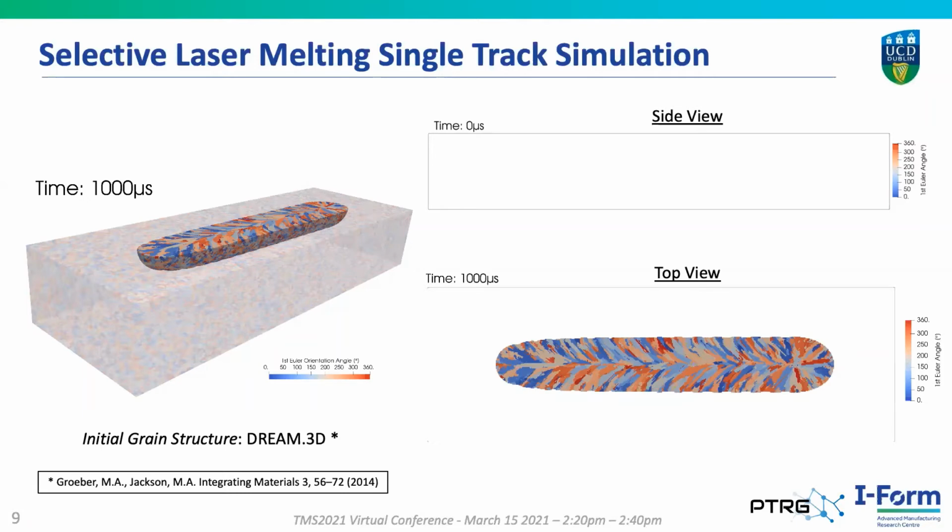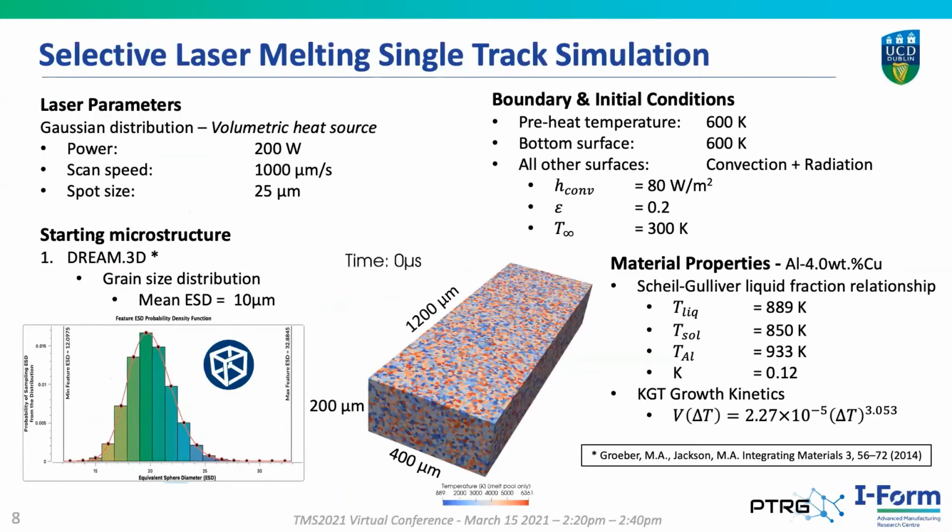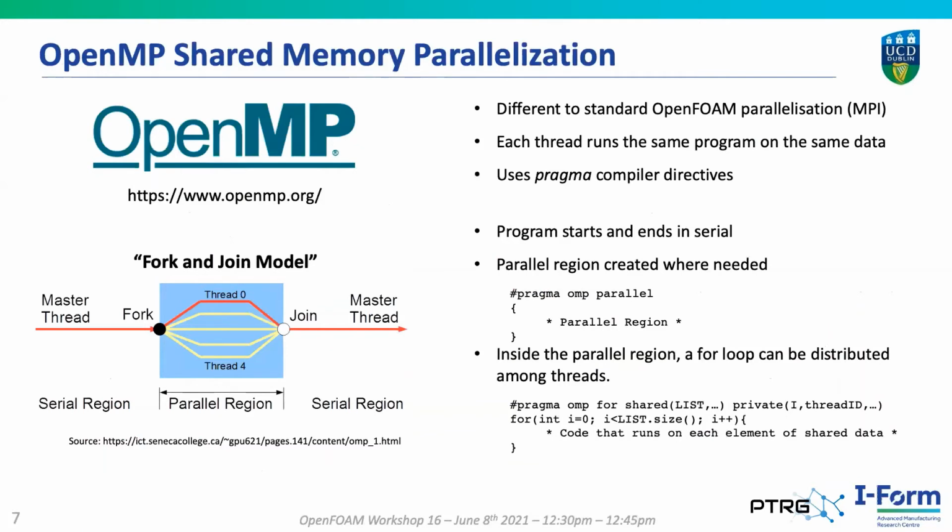Yeah, exactly. So the growth kinetics are generated specifically for a given alloy. Sorry, I'm not sure which slide it is. But the growth kinetics are generated specifically for a given alloy, so if I change the alloy properties, I'll obtain a different growth law polynomial. In terms of handling a mushy zone, my models are considered to be an envelope-based model, so I track the edge of the grain boundary and don't necessarily care about the detail inside the grain. Whilst inside the grain boundary it would be mushy, I don't really consider that. So these models are an envelope-based approach rather than a more micro-scale model like a phase field, for instance, which would track specifically the mushy zone.